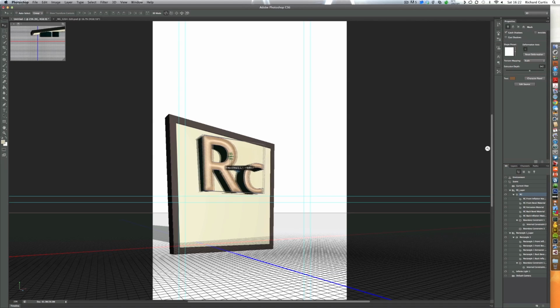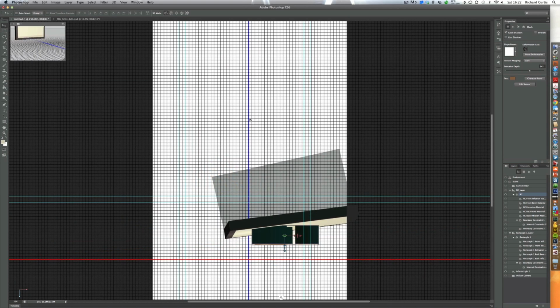So this is all pretty easy stuff. Now it's a little bit skewed, so I want to just make sure that's correct. So I can change the camera to show me from the top what's happening to my 3D perspective. What it means is I can actually get everything lined up by using the top level camera. So if I choose this back plane, I'm able to then rotate this back plane and put it into position and get it square.